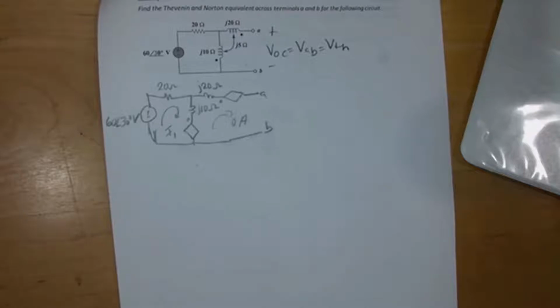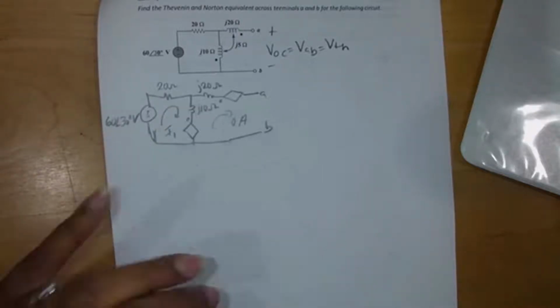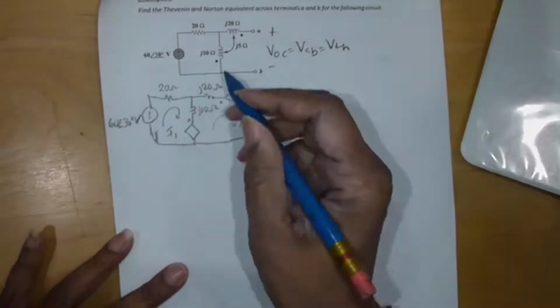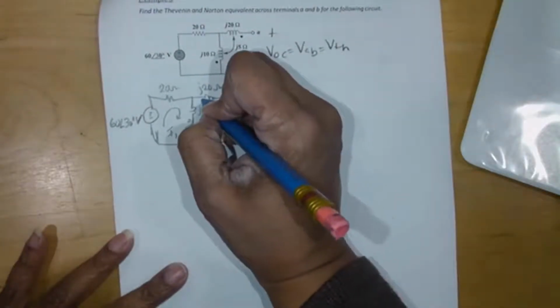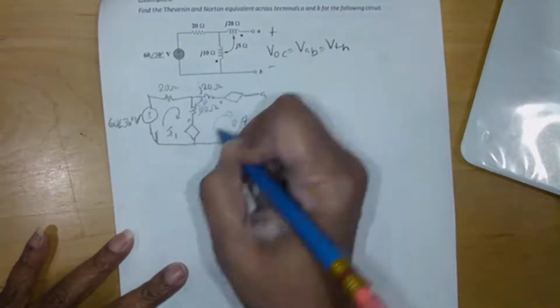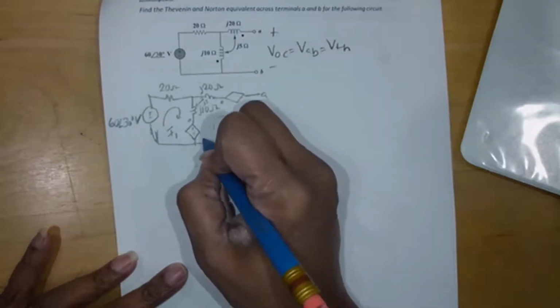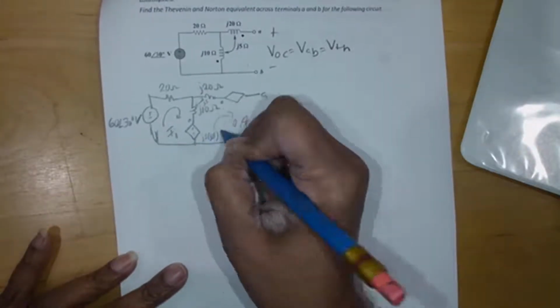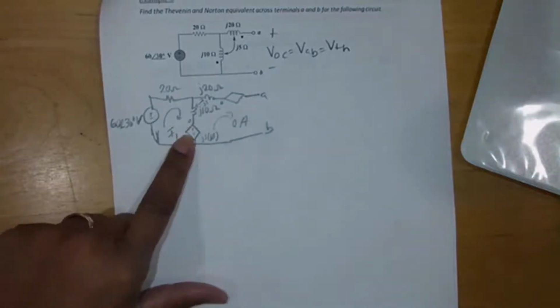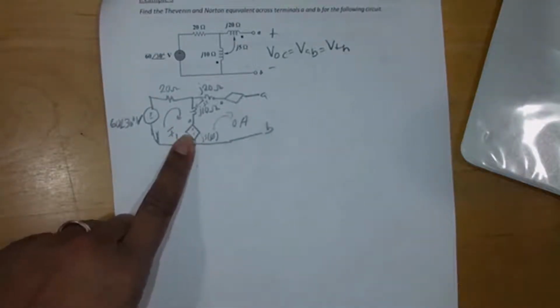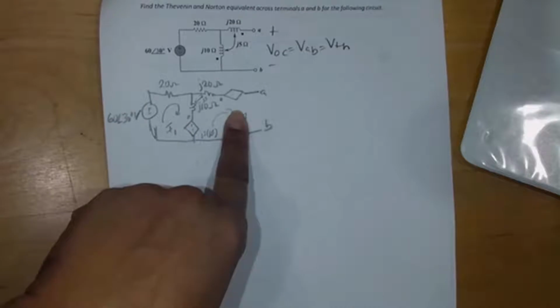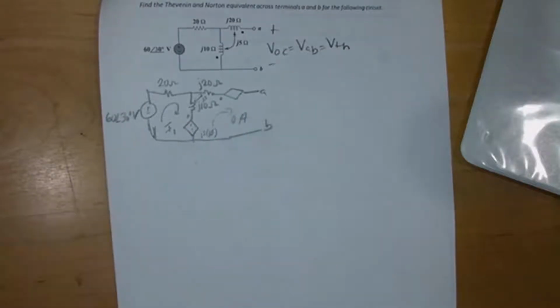Now, because there is no current flowing on this side, even though I have this J5 mutual inductance, this voltage source would be J5 times 0. So it's just 0. This voltage source would be J5 times 0 because there's no current flowing through that right inductor. So that first voltage source is J5 times 0.